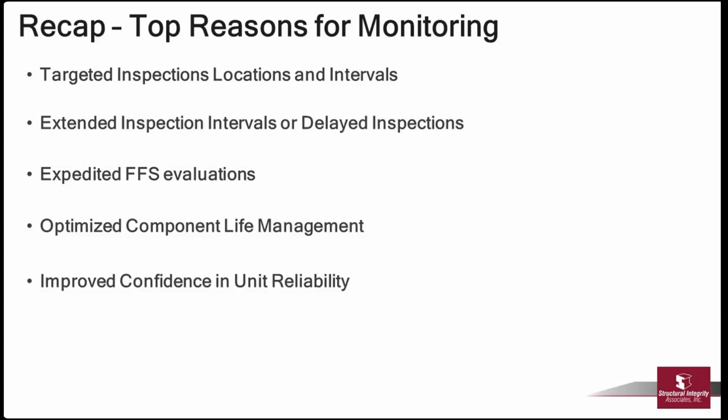I see Robert Chambers is unmuted. Robert, do you have something to contribute there? I think Kane covered it pretty well. It's basically a permanent install of ultrasonic transducer right onto the pipe, and the challenge at higher temperatures above 800 that we've seen is oxidation issues. The sensors certainly operate above those temperatures, but they won't last as long. We're actively working on that, but that's about it.